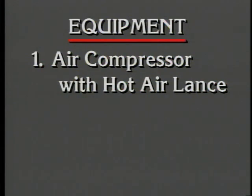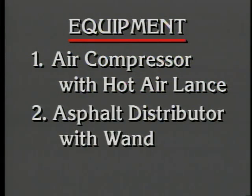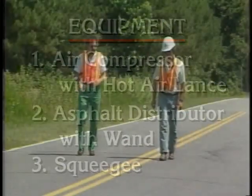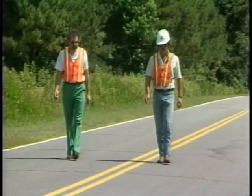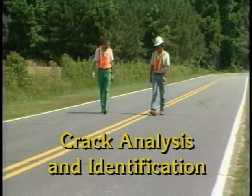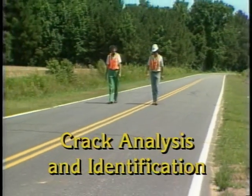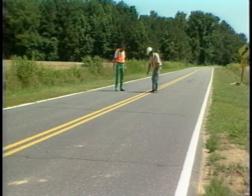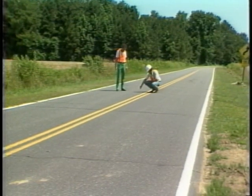The equipment needed for crack sealing includes an air compressor, preferably with a hot air lance, an asphalt distributor with a wand applicator, and a squeegee. The first step in the crack sealing process is performing crack analysis and identification. This is done to identify those pavements which exhibit the type and severity of cracking that warrants crack sealing.